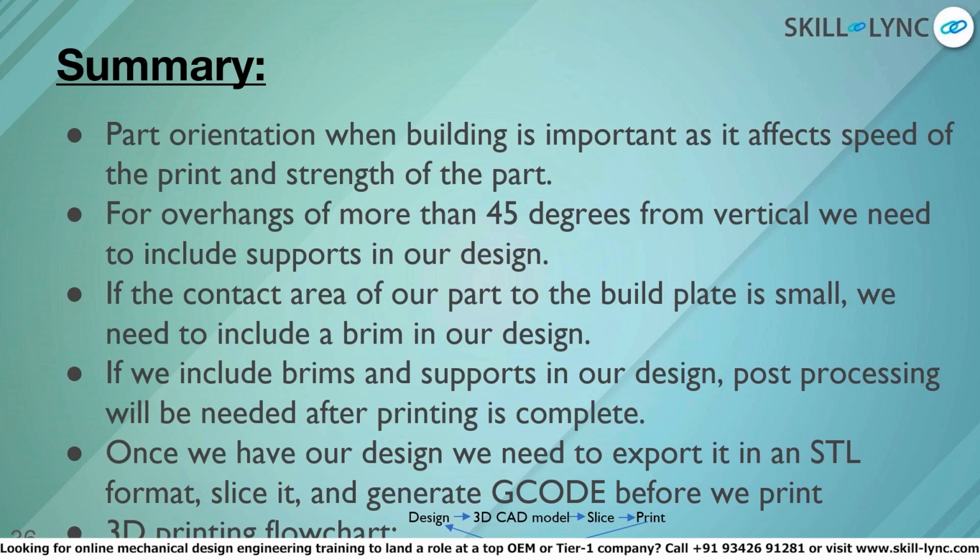So, what have we covered this week? We have discussed that part orientation when 3D printing is important, as it affects both the speed and the final strength of the built part. We have also covered that for overhangs of more than 45 degrees from the vertical, we would need to include support structures in our design. We have also covered that if the contact area of our part to the build plate is small, we will need to include a brim in our design in order to overcome this issue.